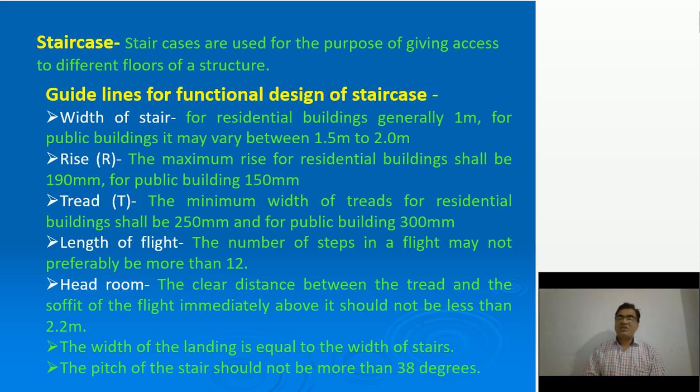Headroom. So, the clear distance between the tread and the soffit of the flight immediately above it should not be less than 2.2 meter. The width of the landing is equal to width of the stair. And the pitch of the staircase should not be more than 38 degrees. So obviously, if you follow the rules of rise and tread, automatically you will get the pitch of the stair less than 38 degrees. So all these are the points related to functional design.